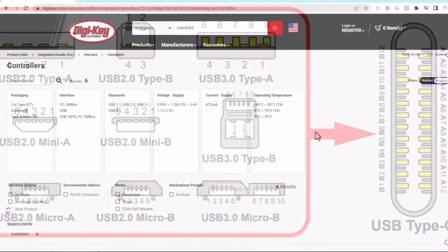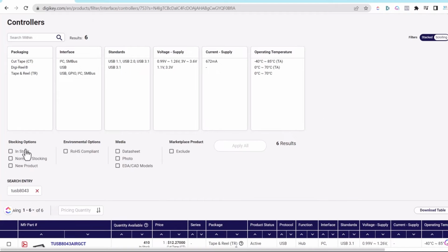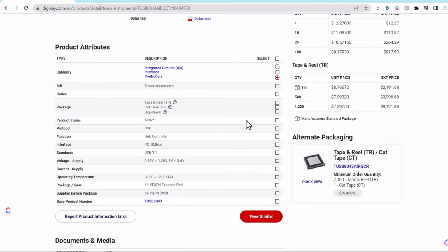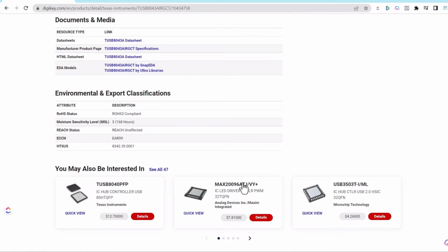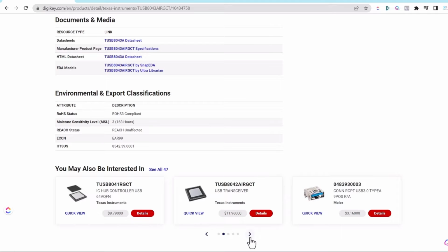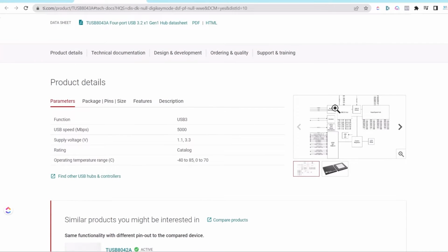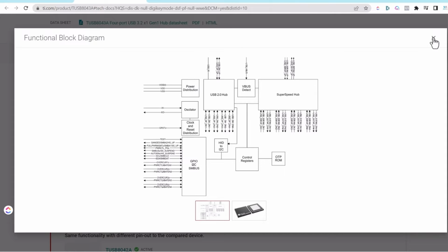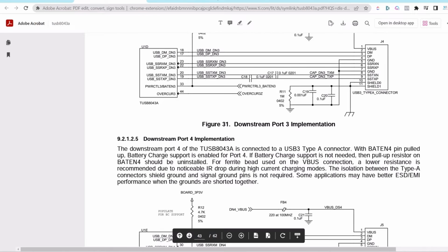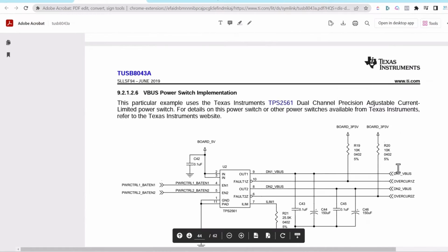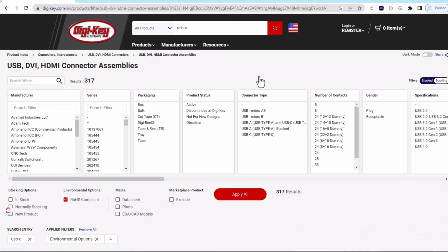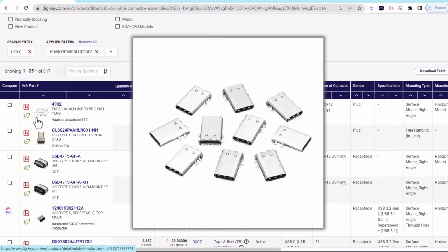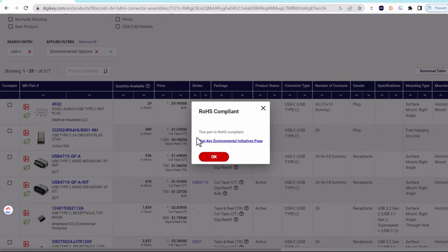Along with component selection, engineers take into account part availability. So especially in a silicon chip shortage, which has died down, you want to look at voltage operation levels for your part, communication protocols, connection types. If a controller can connect to a certain microcontroller chip that's talking to the main motherboard, or if it can't, or if it supports I2C or PCIe, or it just depends. Whether the devices are compatible in terms of their communication protocol, like I just mentioned, if they need pull-up resistors, if they're internal, external, and if everything meets standards for reduction of hazardous substances, also called RoHS for short.